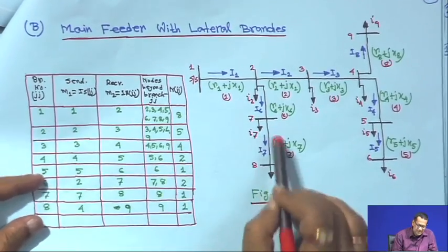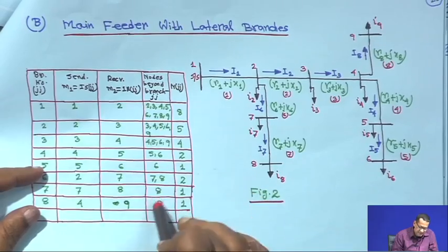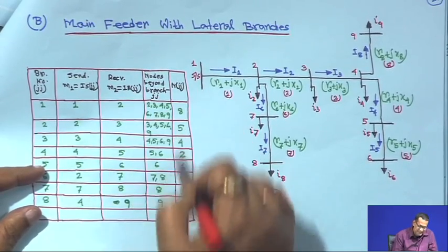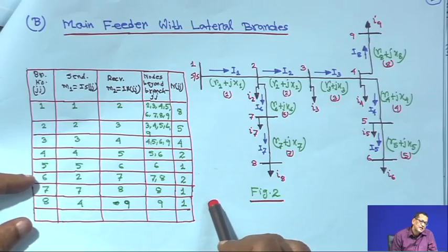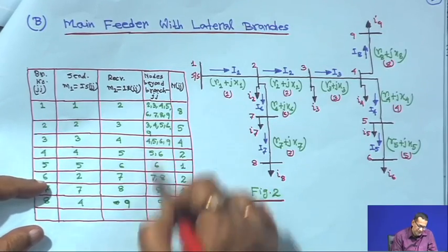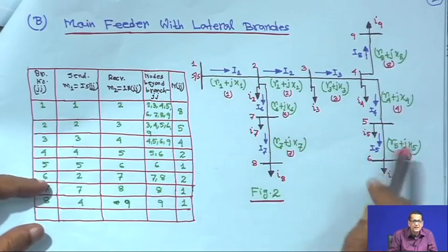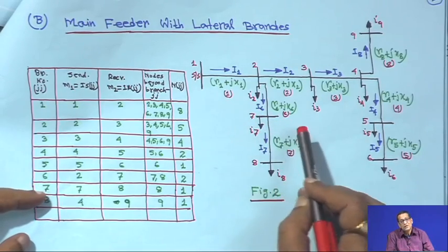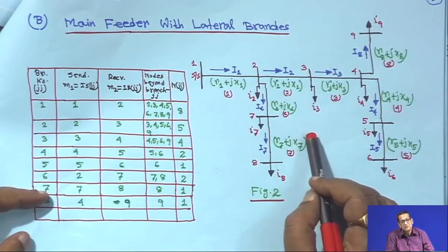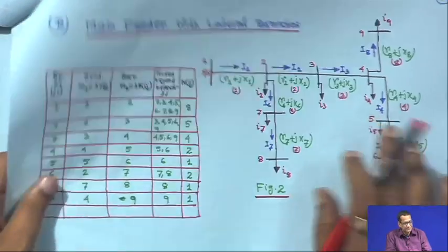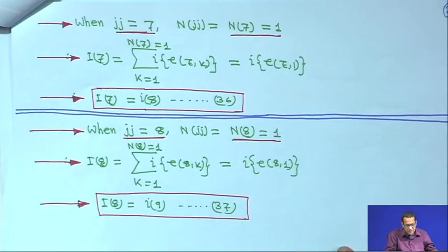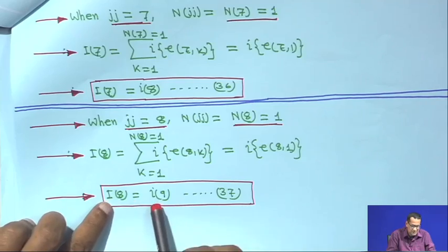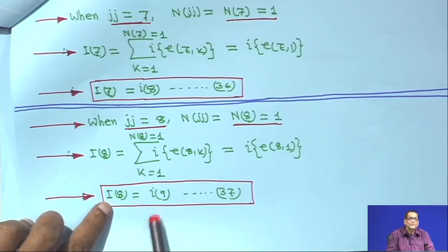even if the diagram is very large, this matrix you can make easily, and you can feed it into the computer to read this data. Then no identification algorithm is required, automatically it will read it and try to find out the branch current, if of course the load currents I1, I2, I3, I4 are all known, but how to compute will come. So, this is how to do the branch current evaluation, which I have shown you.